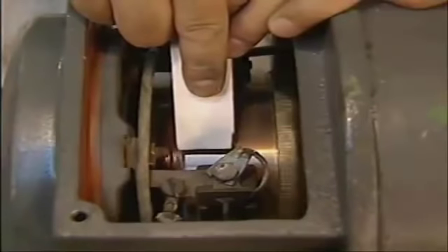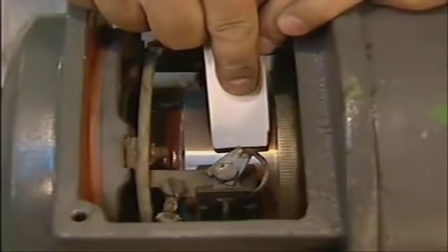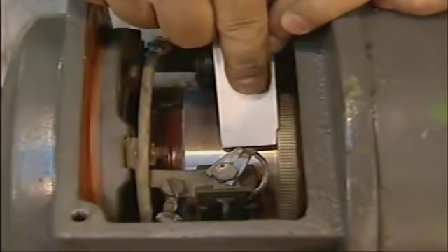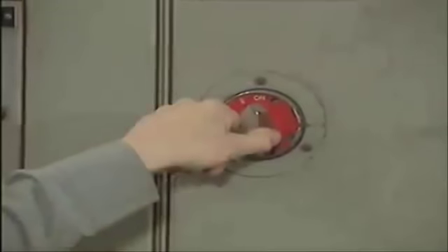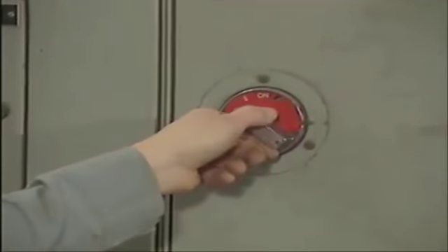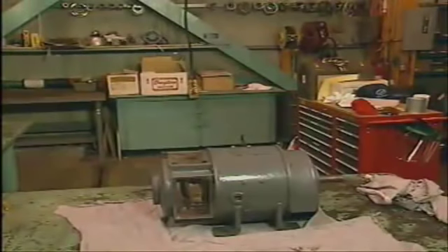When the motor is running, the commutator surface can be cleaned with a canvas wiper or a commutator stone to remove dirt and other contaminants without removing the protective film. Before any other cleaning, though, the motor must be stopped and locked and tagged according to procedures. In this example, the motor is taken to a shop for further cleaning.